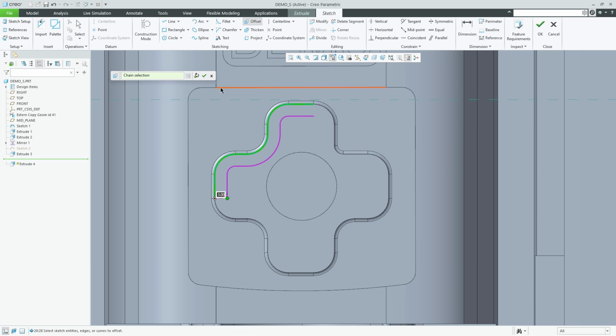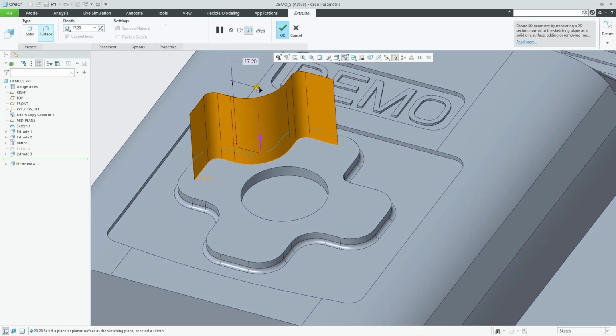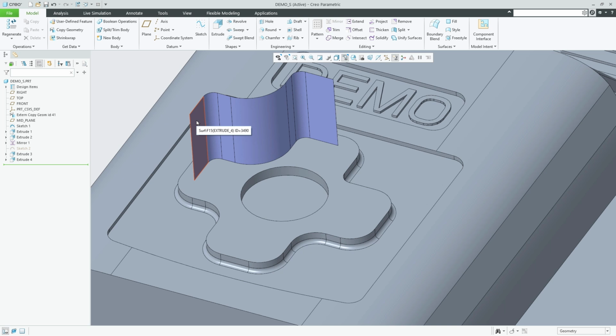When performing replace and modify operations, the geometry IDs for the composite curve segments remain after the replacement or modification of the reference chain or loop. This is demonstrated here with the extruded quilt from the reference offset composite curve chain, with the IDs of the quilt patches going from 3490 to 3478 by decrements of 2.